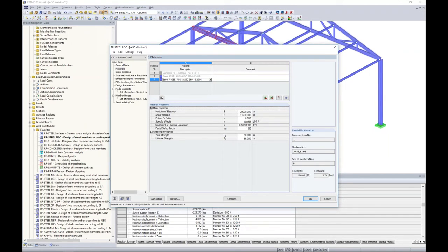Now, this is recognized in the 2016 spec as an approved HSS material, as I mentioned before. With 1085 and 1065, these have more stringent wall tolerances than the previous A500. So what this means is that the code tells us we can now use the full nominal wall thickness for design. This is in comparison to the A500 where we had to use 93% of the thickness. So how do we account for the full nominal thickness with this new material?